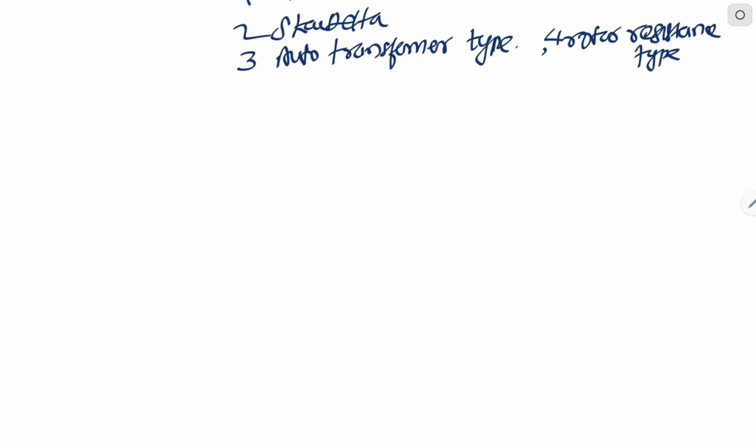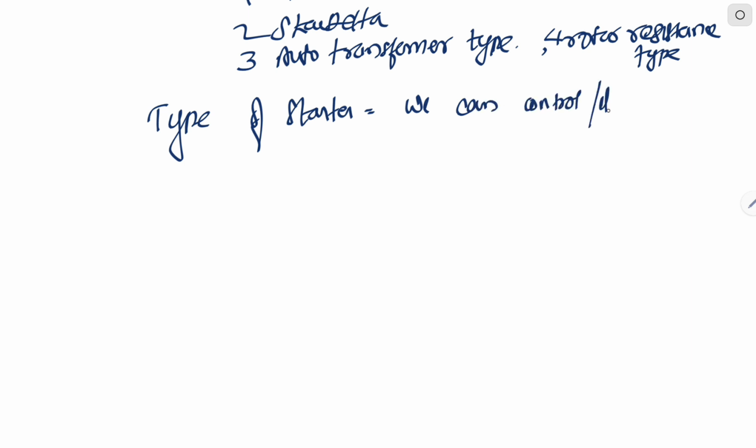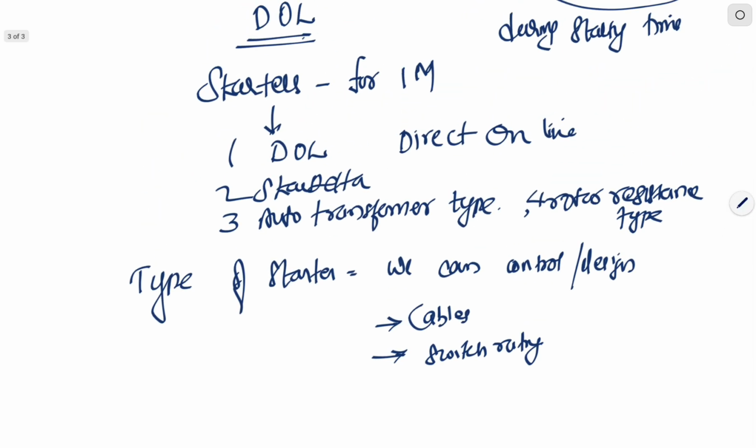Based on the type of starter, we can control or design the cables and switch rating, because for every type of starter, the starting current requirement will be somewhat different.